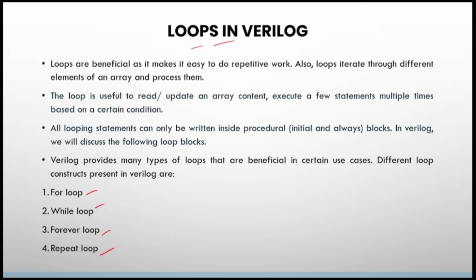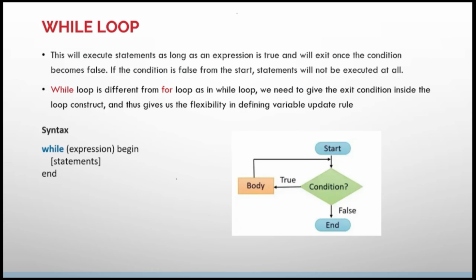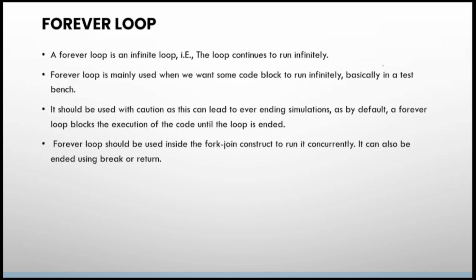So these are the most frequently used loops in Verilog. The for loop you already know; this is the syntax for the for loop. Now coming to the while loop, this is how you will be writing the while loop expression, and this is the syntax for that.